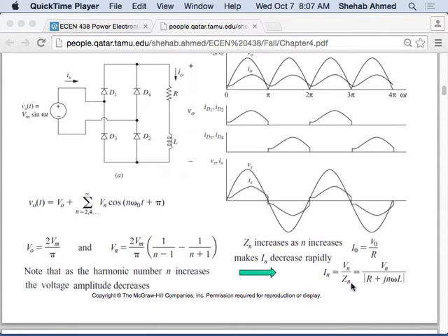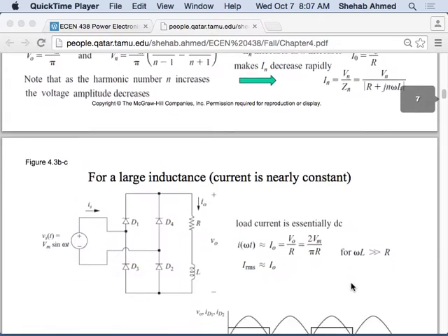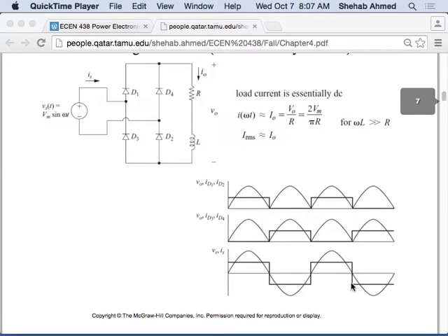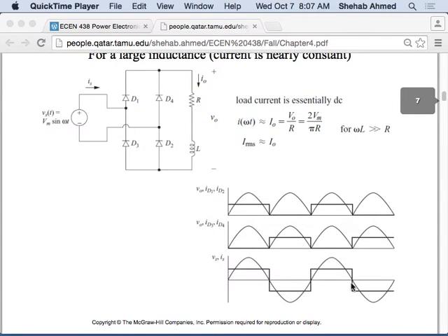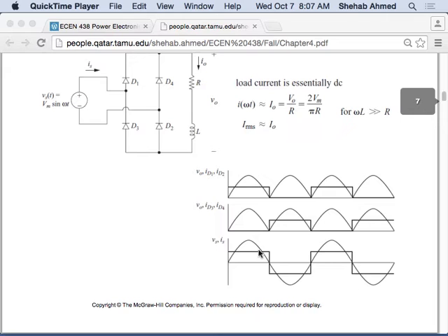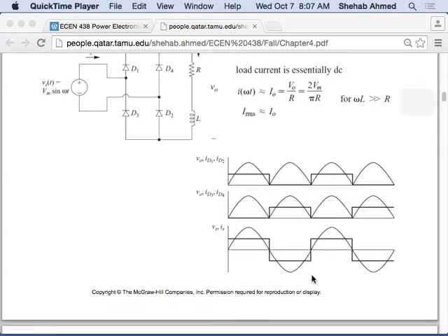But if I can say the inductance is big, so the current is just flat, then the equation for a flat value is just a number. So in that case, you can easily find areas under this rectangle or RMS values or peak values, stuff like that. Just to simplify matters and get you to understand how the circuit functions. So we went through that. Supply current in this case, of course, is just a square wave.